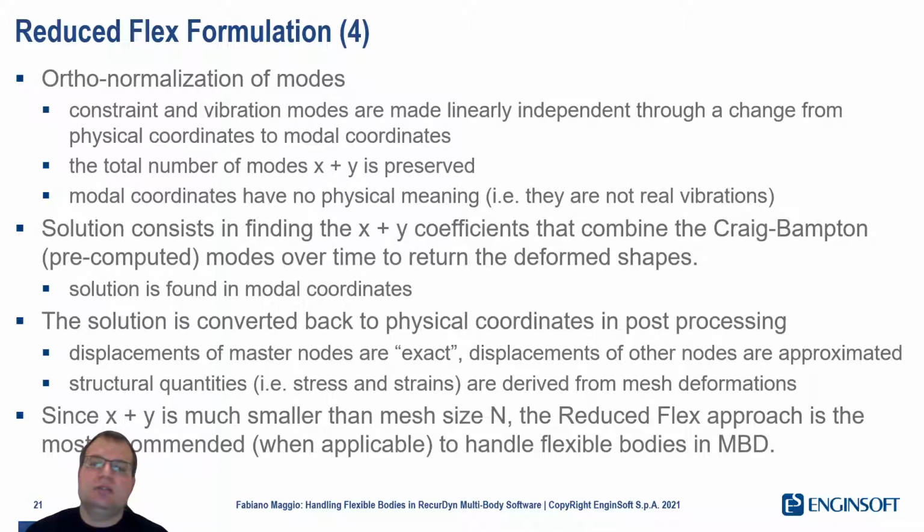Take in mind that the change of basis makes the modes no longer physical. So you start from constraint modes and vibration modes that are all physical, and you end with a set of modes that are non-physical. This is important. So the solution is performed in a set of coordinates that have no physical meaning, but the solver can find them.